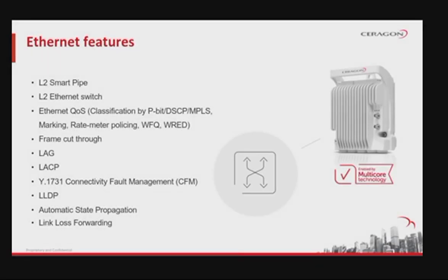IP-20C features a service-oriented Ethernet switching fabric that provides a total switching capacity of up to 5 gigabits per second or 3.125 megapackets per second. IP-20C's service-oriented Ethernet paradigm enables operators to configure VLAN definition and translation, class of service, and security per service, service point, and interface level.